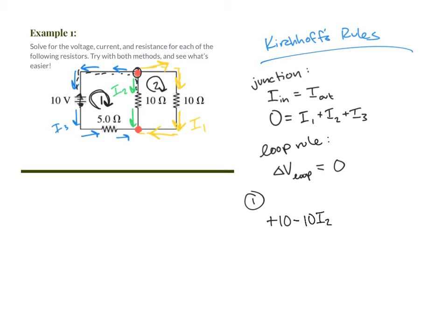As you continue along the loop, after you go through that resistor, you get to a 5 ohm resistor. Now, if you look at the current we drew, we're going through this resistor against the current that we drew. If we're going against the current in a resistor, we're going from the low potential end to the high potential end. So we're actually going to gain some potential there.